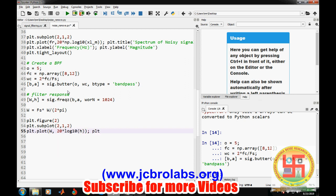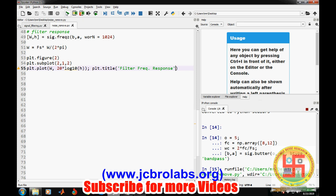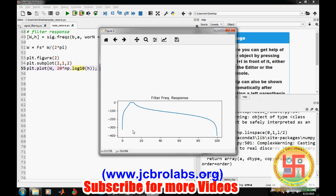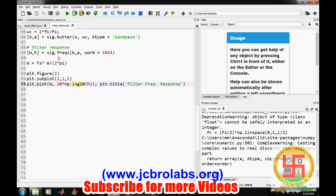Okay, we can put a title, plt.title, that is filter frequency response. Okay, now let's have a look at it. It has to be np.log10. So these are the parts of the programming. Yeah, so we are getting exactly the band pass, and if we zoom in, we'll find we have a center frequency of 10 hertz. So we'll apply this filter on it.